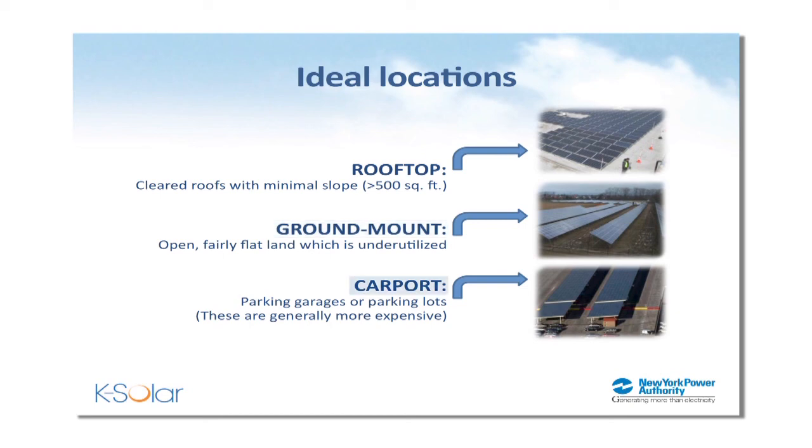Another option is a solar carport. Here again, a parking lot that does not have any shade or obstacles, also with a good view of the southern sky. One thing to note on solar carports, they're generally more expensive because there's a steel structure that has to be assembled for the solar panels to be hosted upon. This adds cost, so the cost of energy from one of these parking lot canopies will be a bit higher from the rooftop or the ground mount alternatives. But if you have no other properties that are suitable for solar, maybe this is an option we'd want to